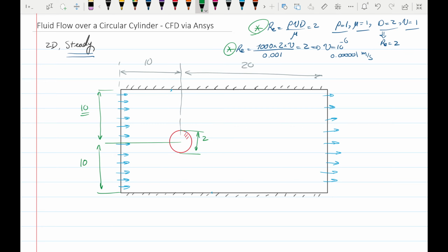We're going to do simulation with Ansys, as I said, and there are 4 different software we're going to work with. First is Design Modeler. There are other options that you can work with. Space Claim is the default. I'm a little bit more comfortable with Design Modeler, which is the older version, but it doesn't matter. It's basically the CAD part, the one where you draw the geometry. And then